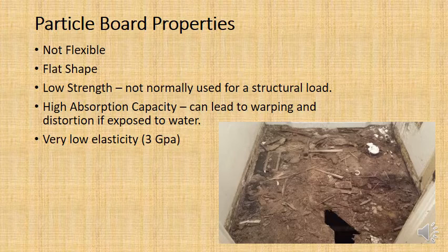So if you're using particle board in anything, make sure it's in a place where it's not being exposed to water. So that picture you see on the right, that was actually a house in Oman, and the idiot who built this house, he actually put a particle board in as the floorboard for the bathroom. So basically every time someone got out of the bath and toweled themselves off, water would go onto the floor and it would slowly penetrate into the particle board, and that's why it's destroyed there.